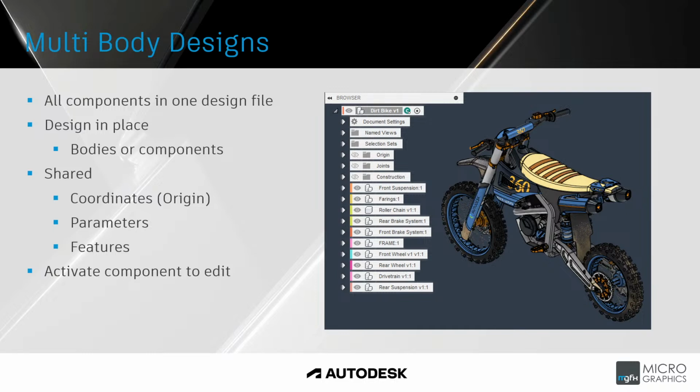This also allows us to create a single parameters table. We'll have one parameters table with all the parameters listed for the entire design. We can then have favorites within that, things like wheelbase, handlebar width, tire diameter, and we can have those parameters drive the different components.